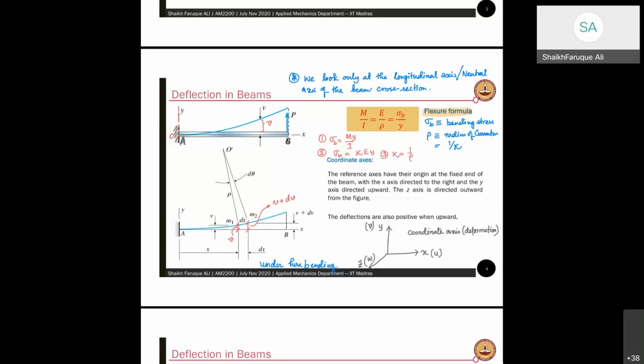Okay. Now look at this cantilever beam that we have. It is fixed here, and the deformation has to abide by the boundary conditions. Deformations cannot go beyond boundary conditions. It has to always satisfy boundary conditions. Okay, never ever make a mistake. Deformations and slopes, these are geometric characteristics of the beam, and they definitely have to support the boundary conditions that are there in the beam.